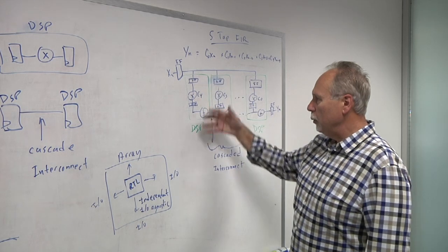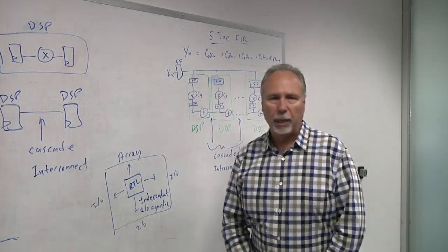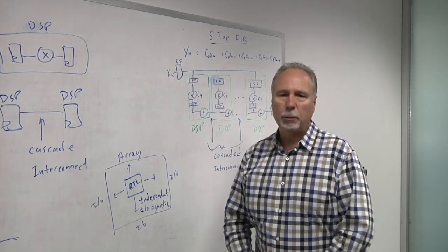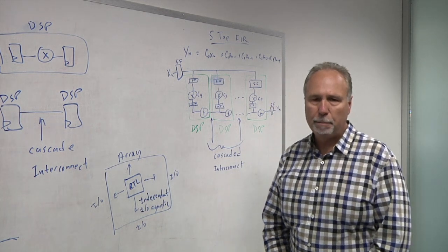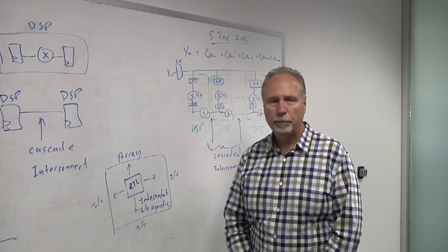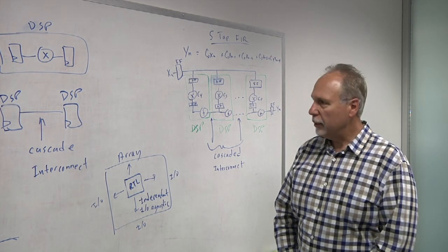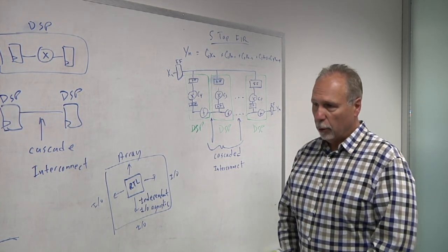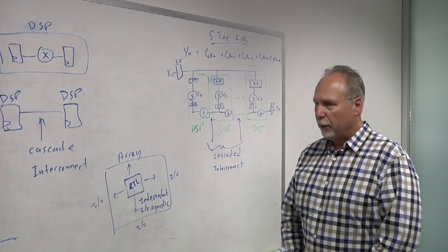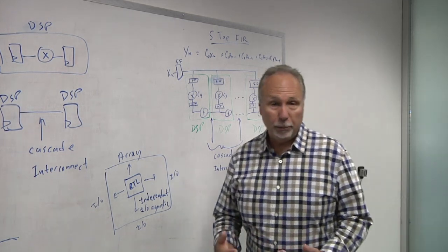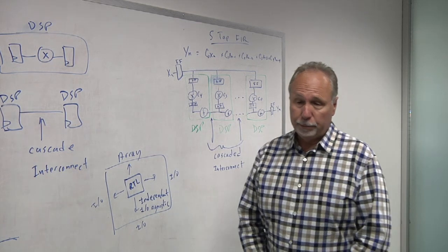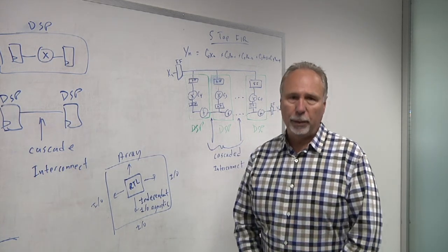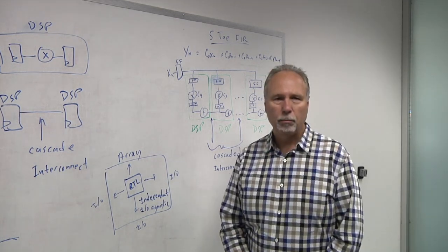And usually with DSPs you want one multiply per clock cycle. Does the density, the process node, have any impact on this? Yes, it does. The smaller node, for instance 16FFC versus 28HPC+, could have 30% higher performance.